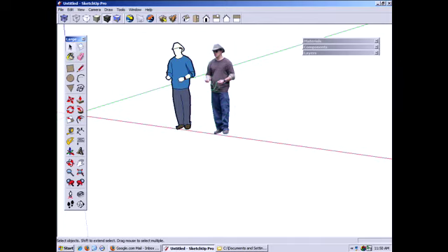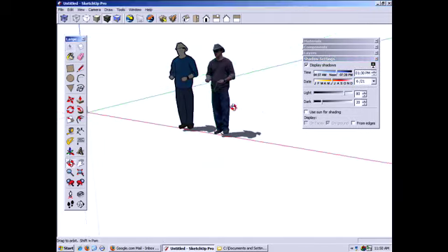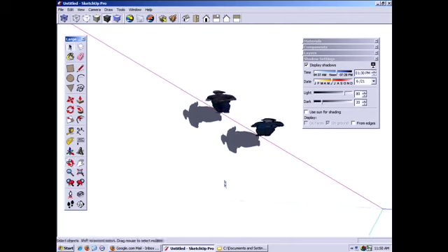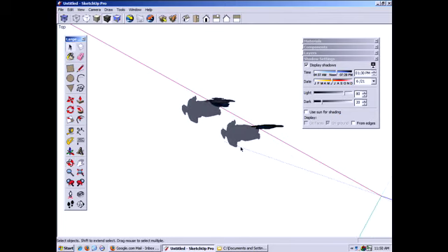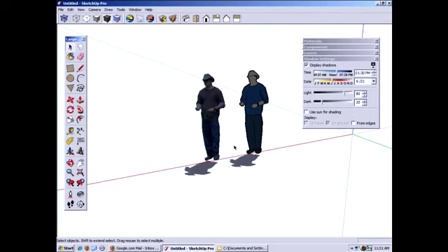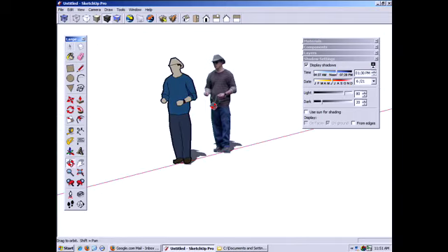That little toggle for shadows face the sun, let's turn the shadows on and show you what that will do for you. Display shadows. This means that no matter how we turn these guys, if the sun truly were over there, you see we'd have nothing because there's nothing going on. They're paper thin. So that's what shadows face the sun means. And generally, it's what you want to leave on. Otherwise, as it turns, you'll get this paper thin shadow that's just a line. So there we go. There's our face me components.